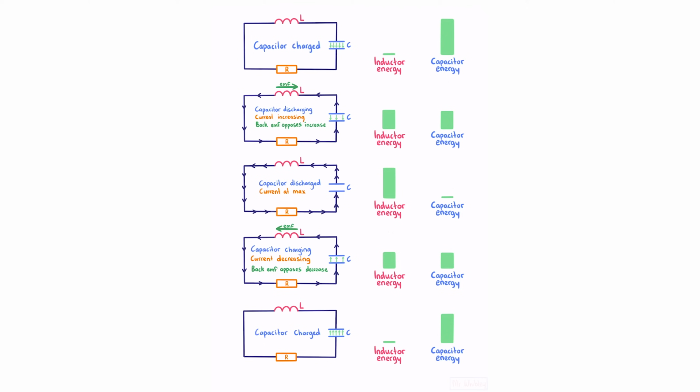So you might note, throughout this exchange, our capacitor energy went into our inductor, and then back into our capacitor. It's important to note that while we have returned to the same stage in our cycle with a capacitor that is charged, our total energy has decreased from the original energy due to the losses from our resistance.